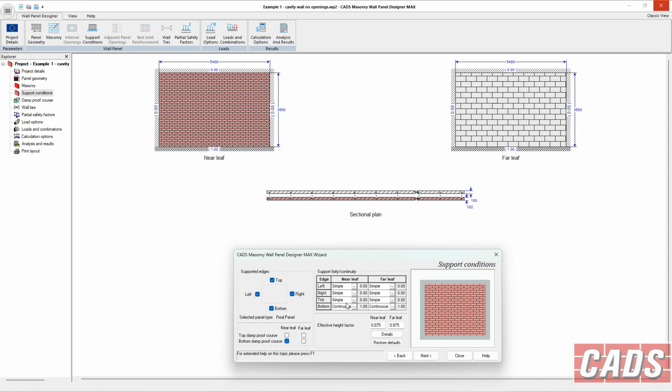Okay, so just tabbing through. You can see we're down to supports here and masonry is there. So you can just see how you can navigate through two different ways there. You've got the support types. Now, the hatching means that we've got a support of some kind. And the double hatching means it's fixed. So if you see here, I changed this to simple. You can see it's changed to just a single hatch.